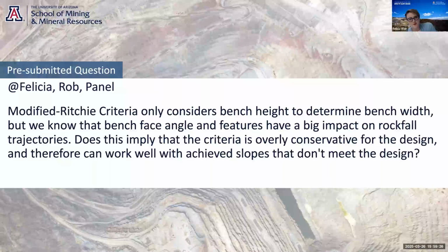I agree with Rob that yes, it can be quite conservative for the design. And I think that's why we now go to other options, like doing our rockfall modeling and trying to understand what are actual appropriate berm widths to manage the risks that a specific site faces. And as Rob talked about already, all of those technologies that exist help us actually look at what the design was versus what was being safely achieved.